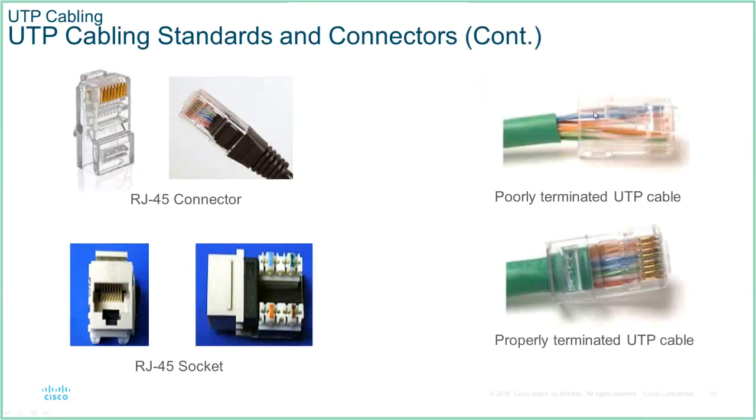There's a fairly long stretch where the individual wires are not twisted together anymore, which introduces the possibility of crosstalk occurring. The mechanical outer sheath is not in the plug, in the connector. So if you tug on the cable, you could actually pull the wires out of the connector.